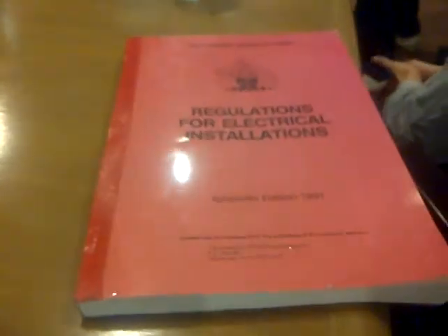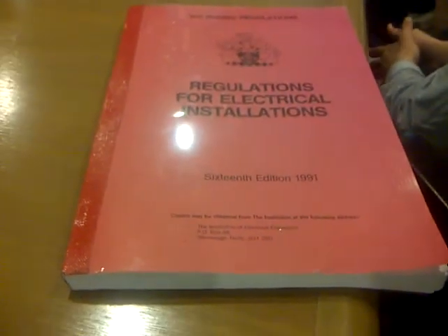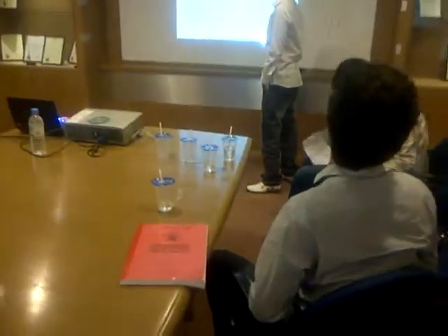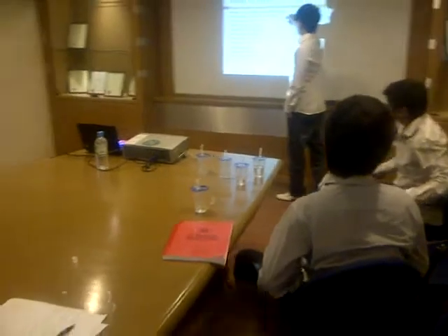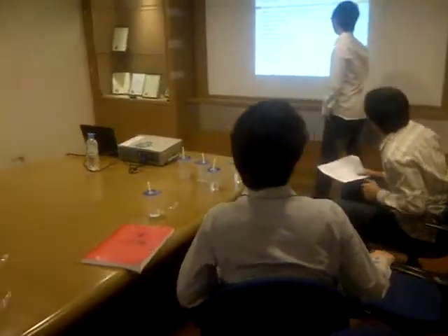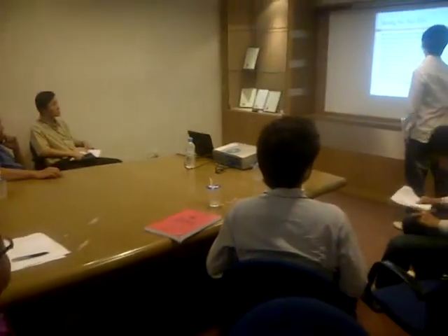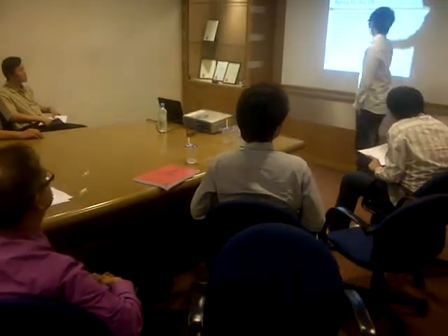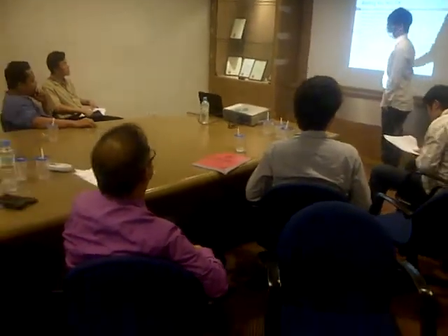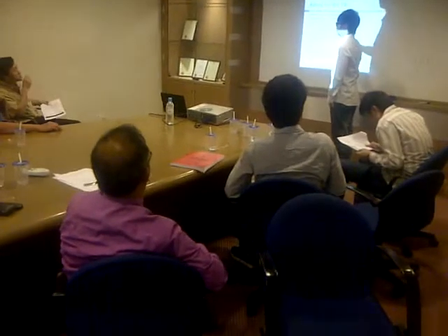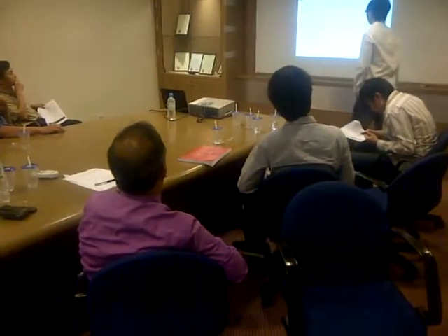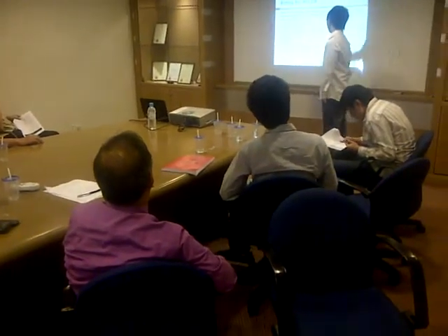There will be the air conditioner system. For the air conditioner, the total maximum load will be 67.8 kilowatt, and the current will be about 120. So I'm using the MCCB rating of 125, and the 35 square copper wire will be used.